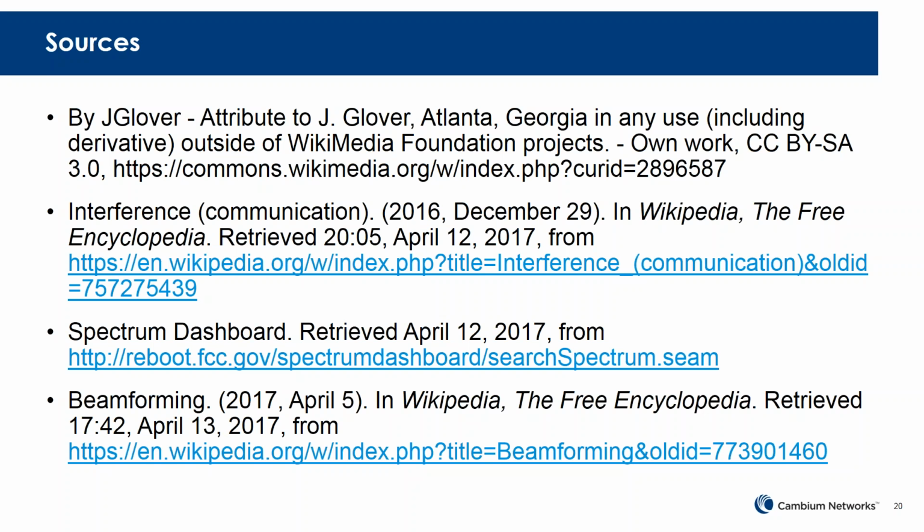You can theoretically use these high-gain parabolic dishes for the access point, but you'll have a very narrow sector. It may only be 5 degrees, 10 degrees wide, and so if you want to cover 360 degrees around the tower, you may be looking at quite a few access points in that scenario. So typically my preference is sector antennas at the AP, at the tower side, and parabolic dishes for any remote.